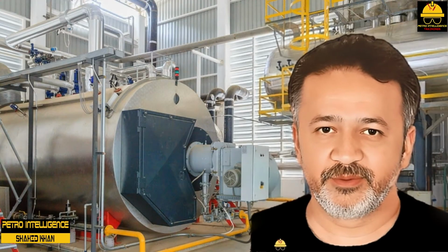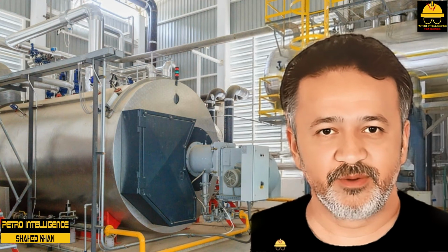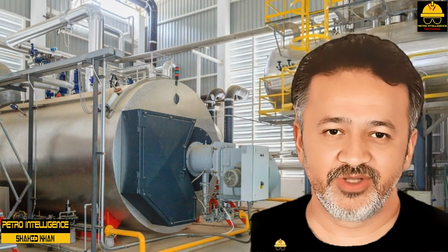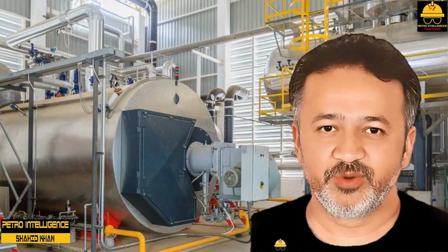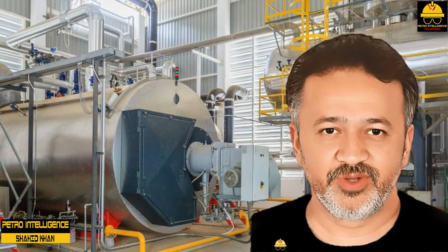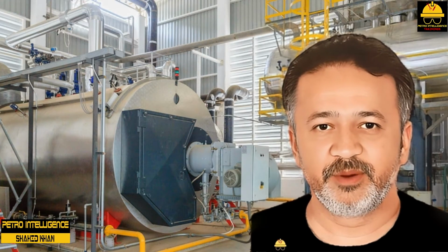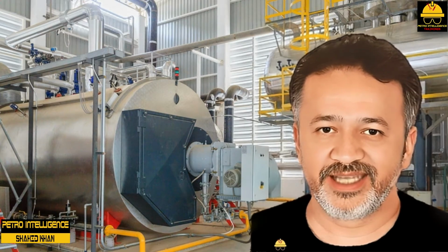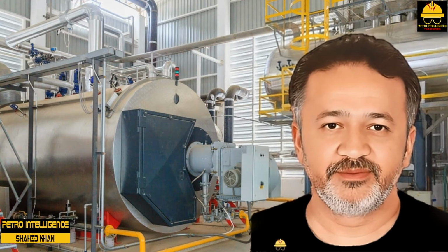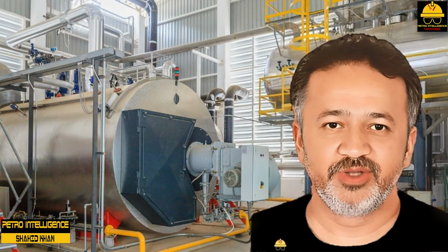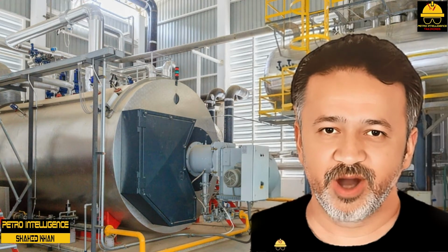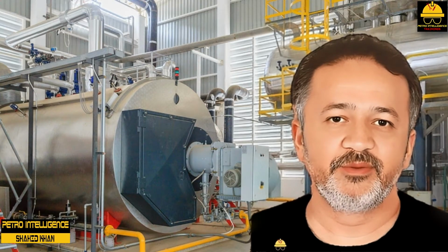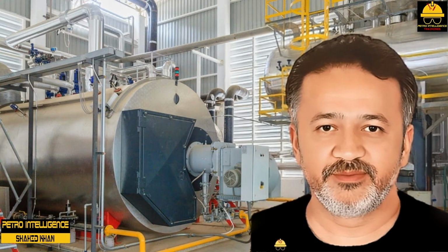Tubes. Boilers contain several types of tubes. Steam-generating tubes are attached to the upper and lower drums. Flow goes through the firebox and back up to the upper steam drum. Downcomer tubes are warm water tubes connecting the upper and lower drums. Risers are hot water tubes between the upper and lower drums. A water makeup line flows into the upper drum.